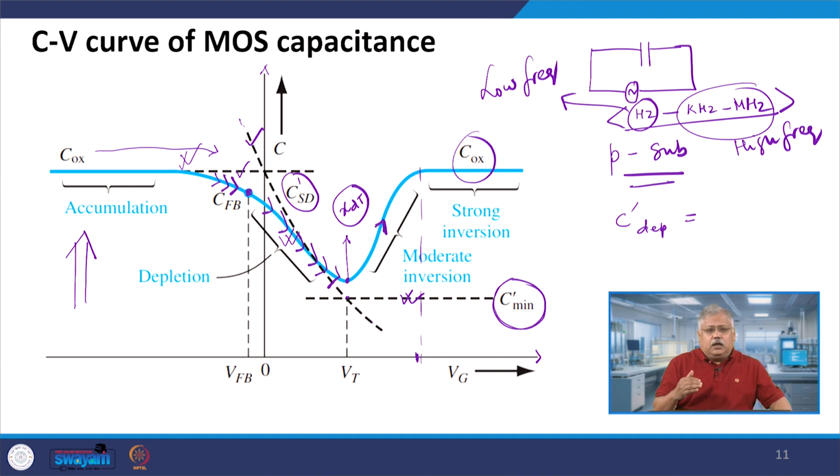And as a result, on the left hand side, when the Vg is very very negative, the bands will be moving up. You start making your Vg higher and higher, the energy band starts to come down. A time comes when they are absolutely flat, that is defined as my flat band. And then if you go on further increasing the value of gate voltage, the energy band diagram goes down, right?